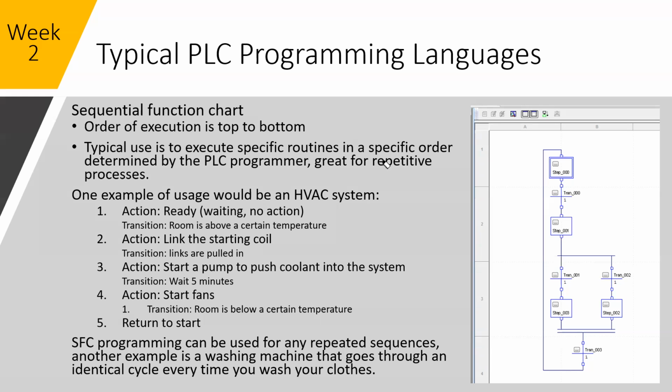Yes, it does. I thought step 2 and step 3 were independent of each other, or more like transition 3 would look for step 3 and step 2 to be completed, hence it will proceed forward. Yeah, so if you wanted to do that, then you would actually stack it differently. So you would go like this, you wouldn't have that one, and you would then come up. So you want to first SFC series. Yeah, series. You would do everything in a very specific order. Oh, I see. This is like an or condition. Okay. Yeah. So this is exactly that.